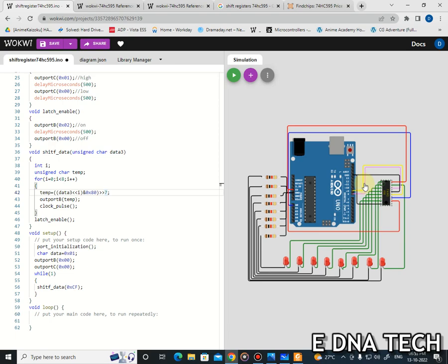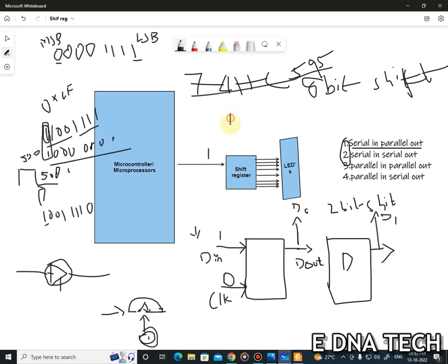Port B will have pins from 0 to 7. It is the output register of port B. So we want to write the values on this register. The 0th pin is connected to our DS pin, so we want to have that value on the DS pin. If you send this value as it is, it will be 0x80, but our value must be 1. So we want to shift this 0x80 by 7 times.